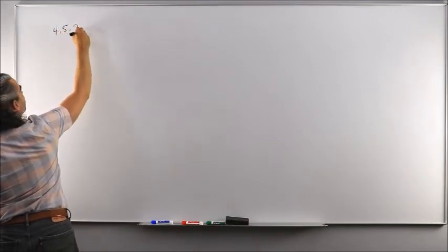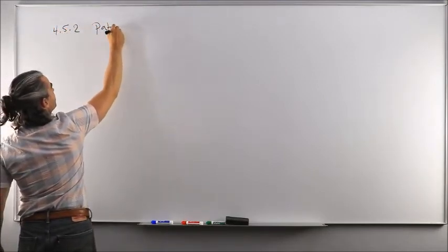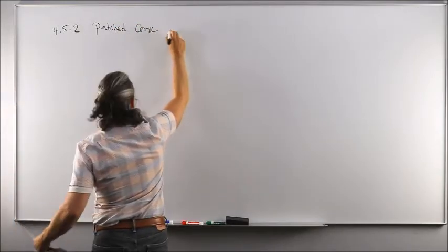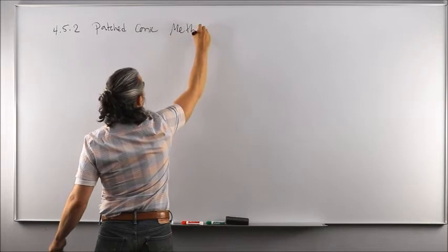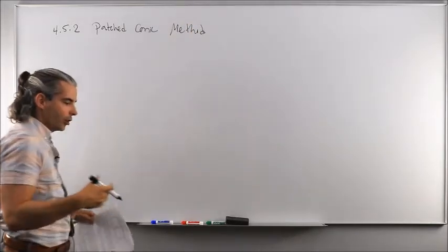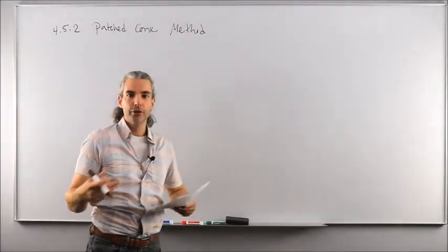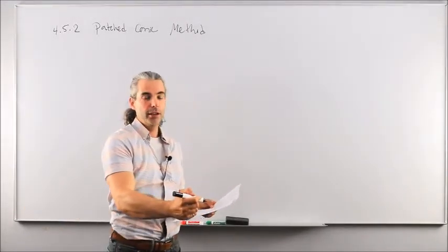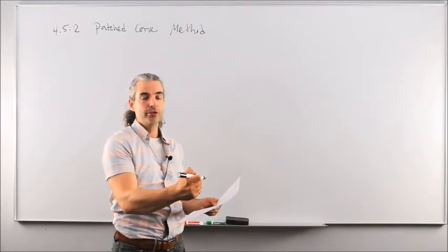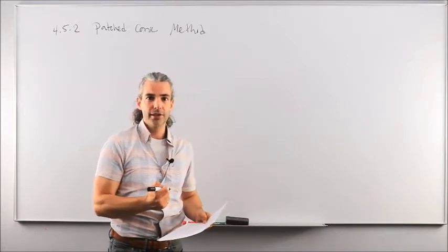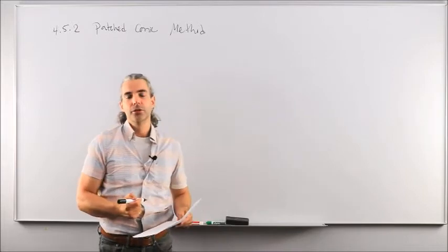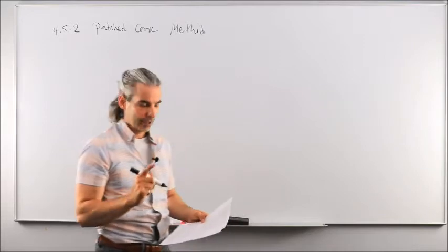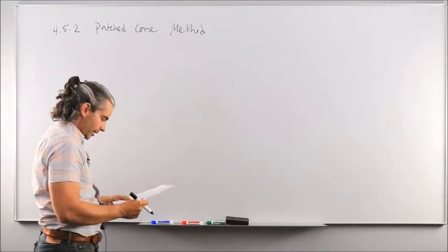Because we are patching conic sections together, or different orbits and trajectories together, from the hyperbolic trajectory, we're going to patch the end of that trajectory to an elliptical transfer orbit around the sun, and then patch this elliptical transfer orbit to another hyperbolic trajectory upon arrival at the target planet. Hence the name patched conic, okay?